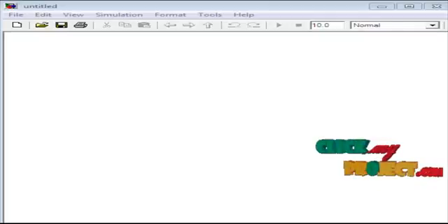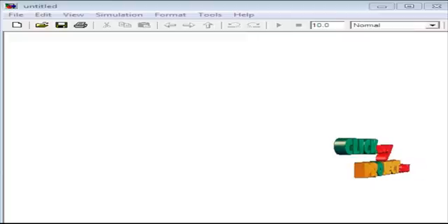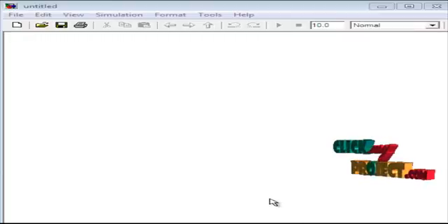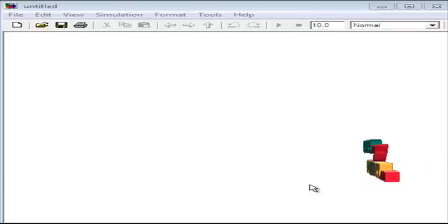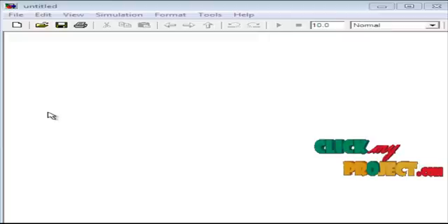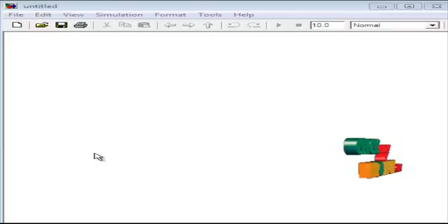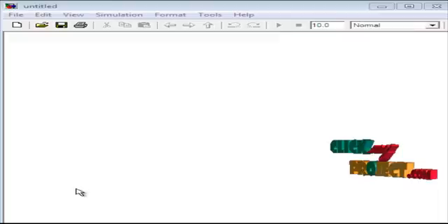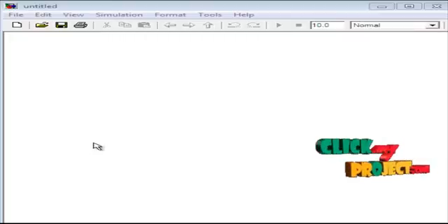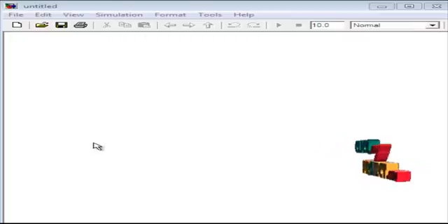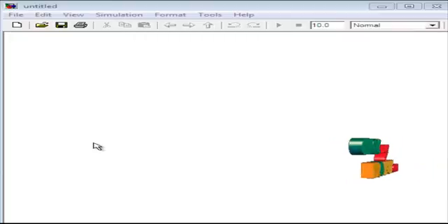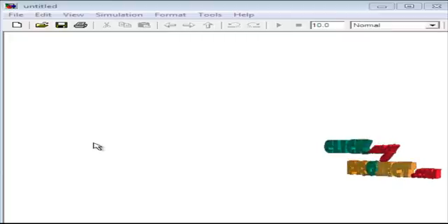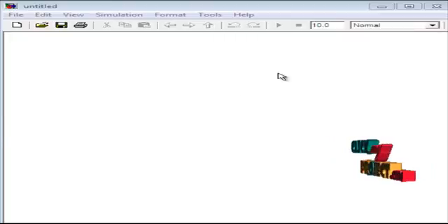Now we are going to discuss the running procedure. Our product is developed by MATLAB simulation, the simulating tool. With this tool we develop the product, the DC to DC converter model. The DC to DC converter model takes an input of 68 to 78 volts, and then we get an output of 8 to 12 volts, maximum 15 volts. The main stage is the buck converter using these blocks.